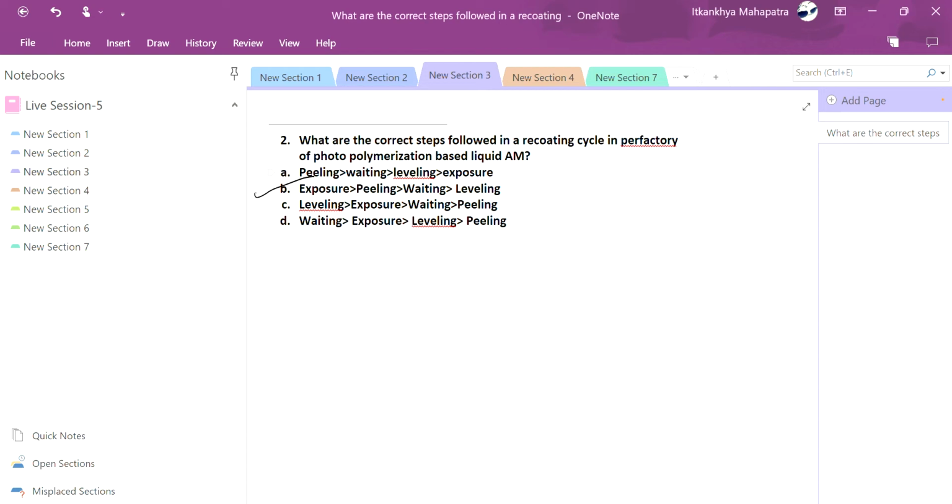Perfactory has various key features: reduced cycle time, minimized need for support structures, no lasers, and the mirror lifetime is 2200 hours. Apart from it, the exposure is done by the voxel curing method.